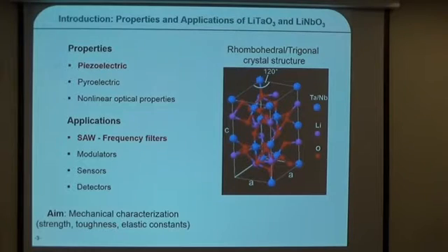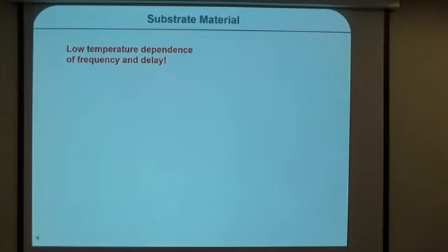What I now wanted to investigate were some mechanical properties, because these devices are exposed to thermocycling and drop tests and so on, and therefore we need some good strength values, also toughness values, and elastic constants are available. So I used some methods, biaxial bending and nanoindentation.